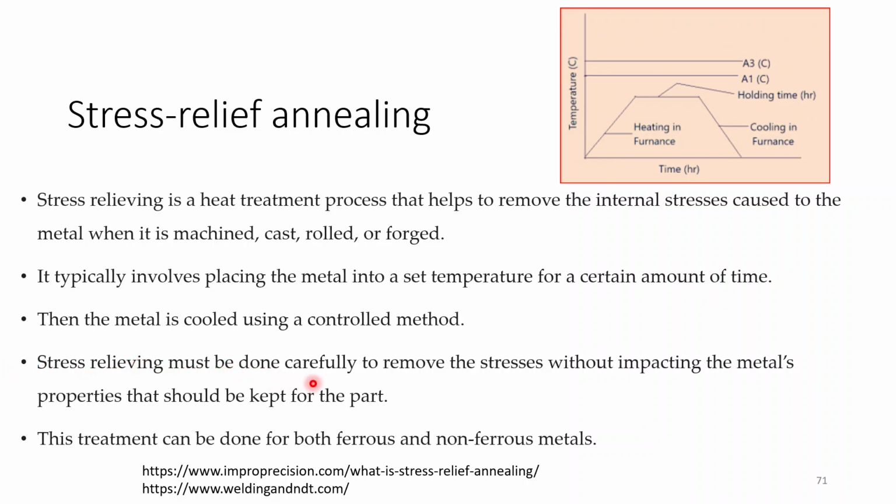Stress relieving must be done carefully to remove the stresses without impacting the metal's properties, which should be kept for the part. This treatment can be done for both ferrous and non-ferrous metals. And the heating cycle is shown here, below the lower critical temperature.